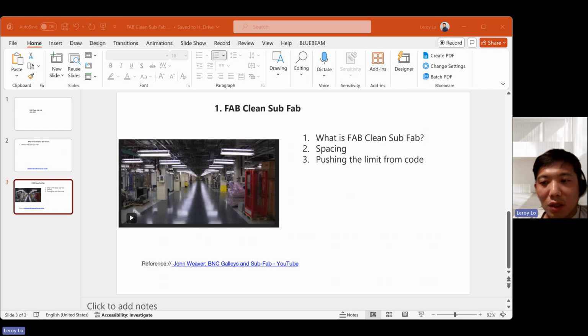And then from the architectural side, normally you will need to ask a lot of questions, like where the chemicals are going, and what CRC is called. CRC stands for chemical resistant coating. We have to think about the chemistry of these materials, because these epoxy chemical coatings are only compatible with certain chemicals. We have to lay out the trenches, which are an important part of getting rid of these chemicals, since they are very corrosive or highly flammable. All of these things need to be looked into.